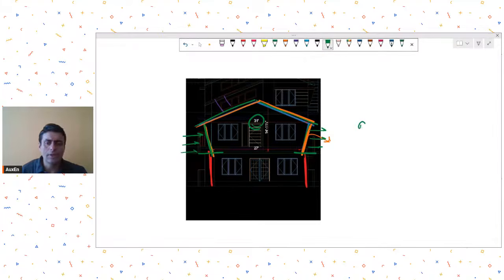Okay. So the additional moment due to the slanting nature, you have to design for that. Okay. And in these types of structures, you will have to be slightly careful about the stability also, although this will be stable because this is sort of getting balanced. But for lateral loads like wind, you may have to check its stability.